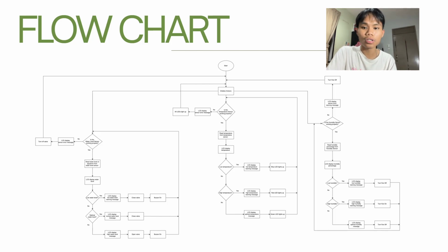And then number 2, it checks humidity, automatically controlling a fan to turn on if the humidity is high or off if it's low. Finally, it checks the water level, sounding a buzzer and controlling a valve to alert the user and correct levels if the water is too high or too low, ensuring the system returns to the beginning to continuously monitor the environment of the hydroponic system.